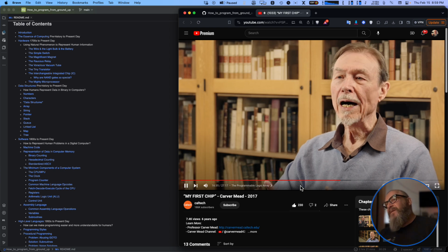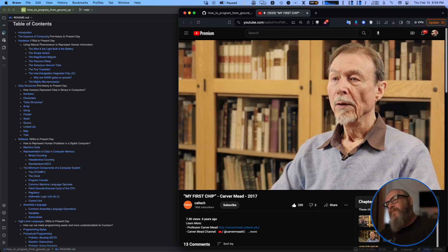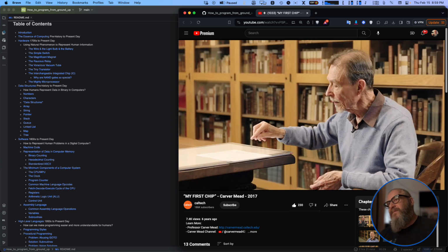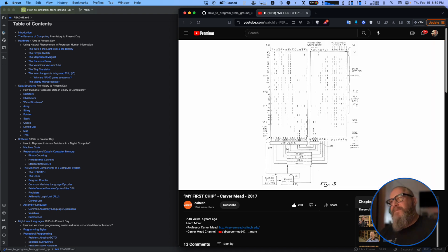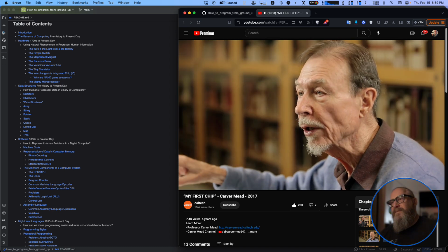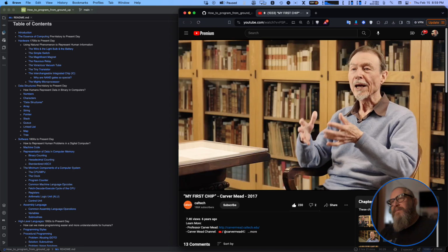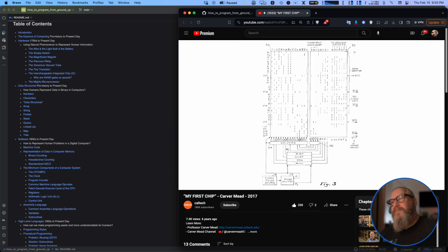That was a big aha for me. I can make a simple, regular arrangement that can generate any logic function. This structure then became a way of doing logic where I could do all the electronic design, I could get the timing right, without regard to what exact function was being done. And then I could program that function later. So it became programmable.